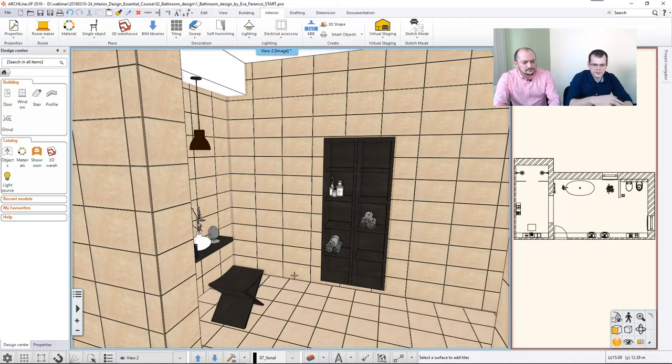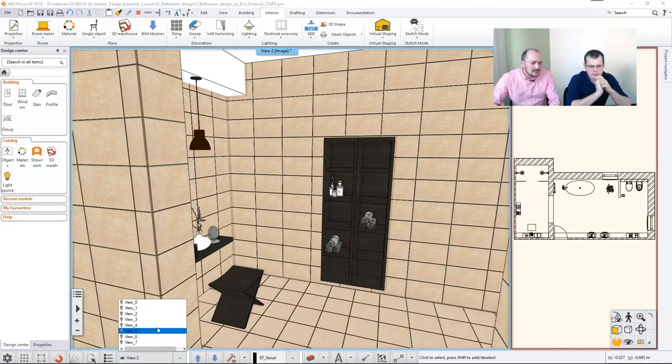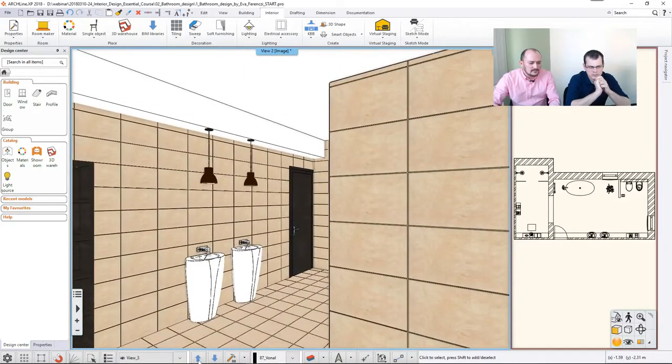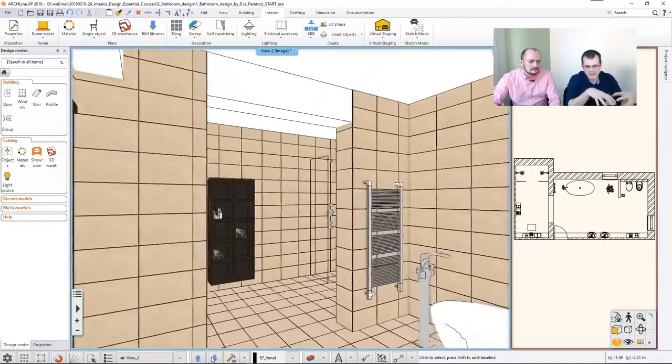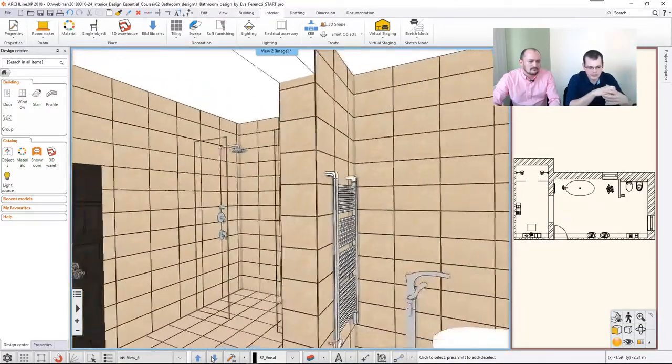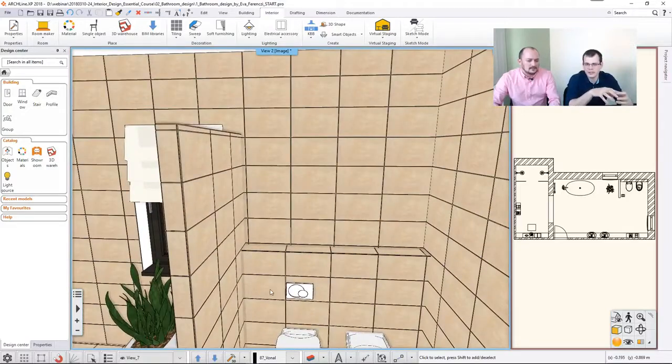Now, what if I want to be a bit more elaborate in this? How about I want to add some extra shapes or forms or design elements, maybe change a couple of tiles? Yeah, for that, I think I have a view already saved. Let me just go through these views. While you navigate, I'm just reminding everybody that these are pre-saved views, perspectives, which are very good when you're working in a very narrow area where navigating with the mouse, the scroll and shift key would be a bit cumbersome, so you can just preset views and navigate where you want to go.